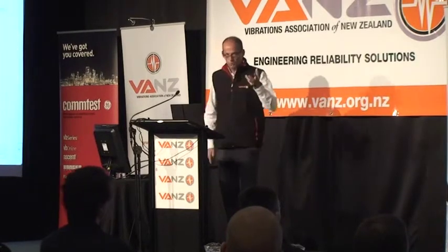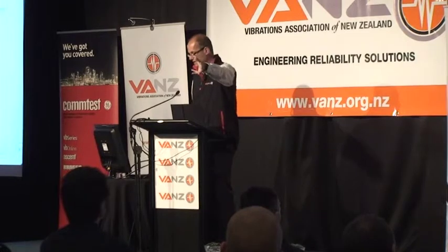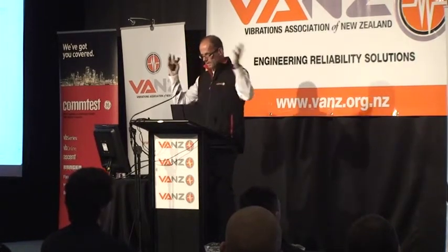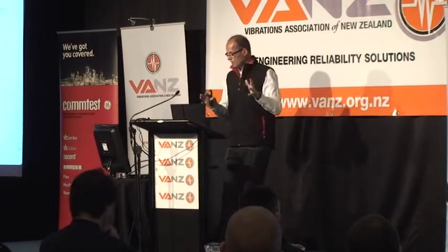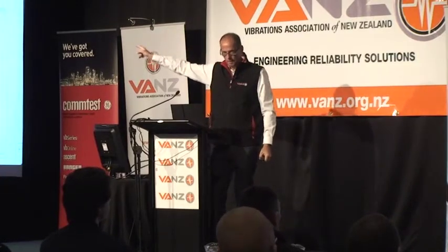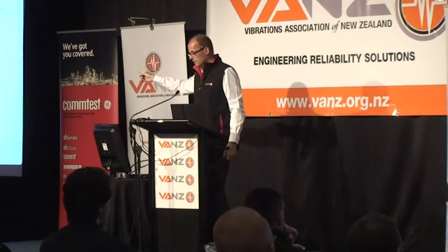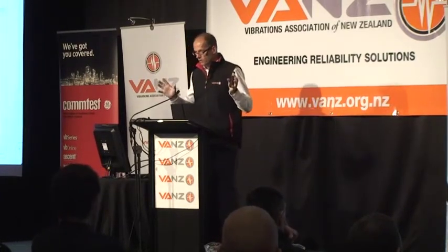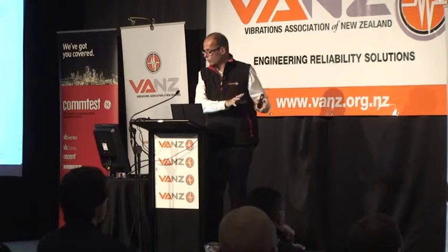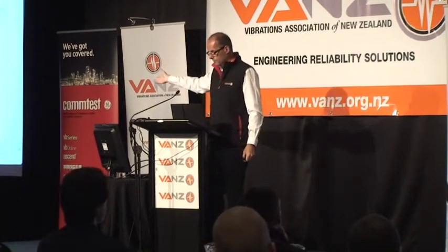Now the key with all of this is never to just detect that the problem exists, replace the bearing and say my job's done. Your job's not done, because you've got to ask the question, why did that happen? Why was the bearing damaged? Because if we don't ask that question and fix the root cause, we'll just be back here after a little while fixing the same problem.